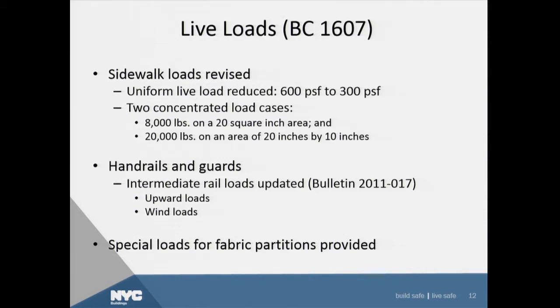Sidewalk live loads have been revised. This is a big change. This is something that we have historically had in New York City, the 600 pound per square foot sidewalk live load. That has been reduced after our committee did a lot of research on the types of equipment and vehicles that emergency service personnel use and what are the live load requirements in other municipalities and areas. That was changed from 600 pounds per square foot down to 300 pounds per square foot.